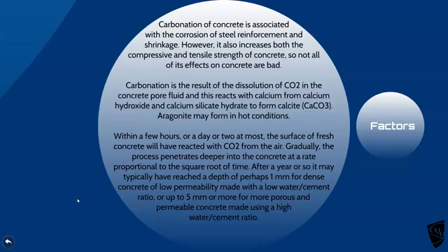This is really considered, as I mentioned earlier on, about the corrosion of the reinforcement in there. Carbonation is a result of the dissolution of carbon dioxide in the concrete fluid. And it reacts with the calcium hydroxide and the silicate, and so on. Chemical lesson, don't worry about it. Within a few hours or a day or two at most, the surface of fresh concrete would have reacted completely well with the CO2 in the atmosphere around it.